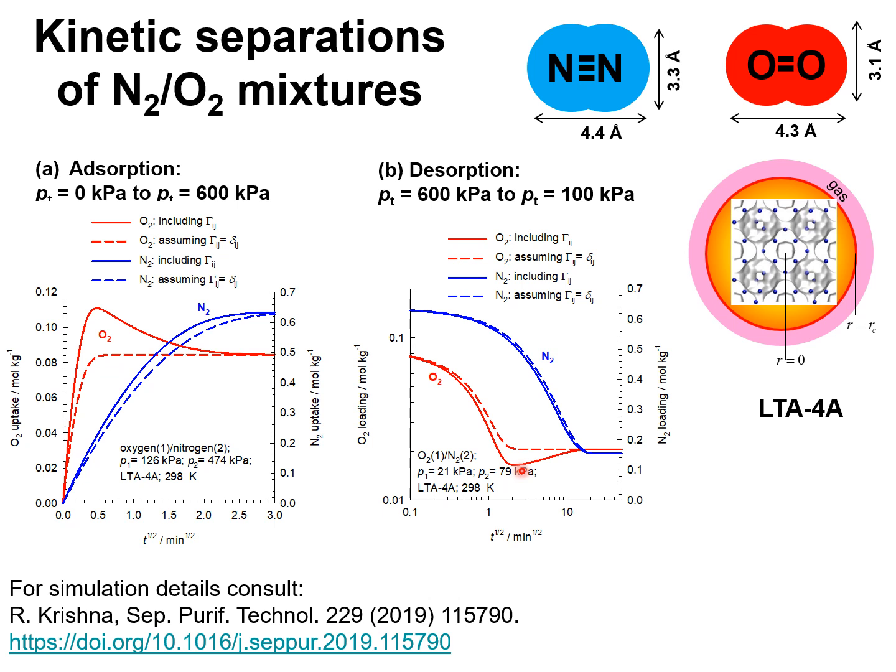firstly, thermodynamic coupling effects are included. This is shown by the continuous solid lines, and the dashed lines are the corresponding simulations in which thermodynamic coupling effects are considered to be negligible. We note that oxygen experiences an undershoot in its approach to thermodynamic equilibrium. Therefore, thermodynamic coupling effects induce transient overshoots during uptakes and transient undershoots in mixture desorption.